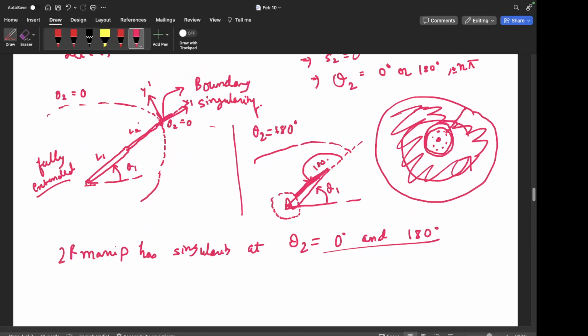Basically, we would keep all our trajectories well inside the workspace, not go close to the edge of the workspace, because, as you would have seen in the manipulability lectures which will be discussed ahead, as you go closer to the edge of the workspace, the manipulability ellipsoid gets very flattened and in the end becomes a straight line. So you lose manipulation ability.